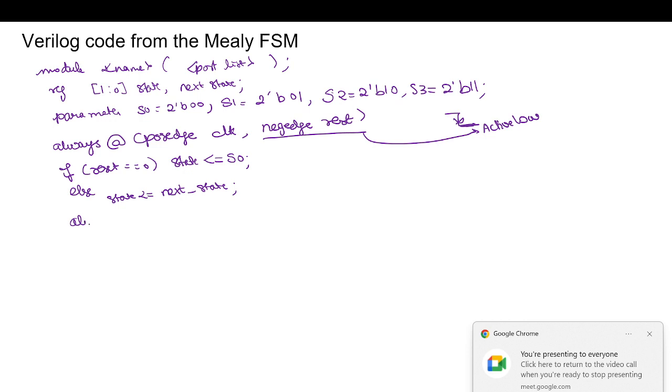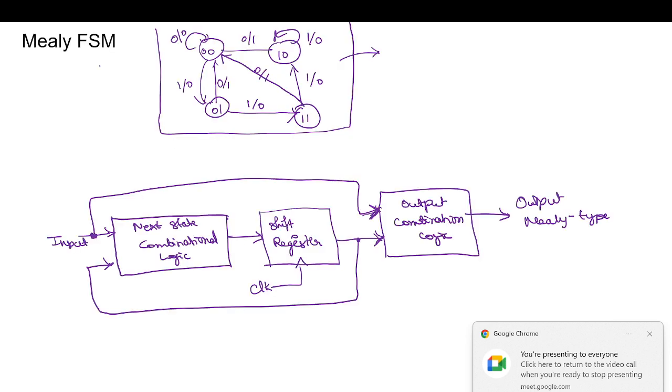And then for this always block, I have not written begin and end. So after this one statement, the next statement I will write inside another always block, always at the changes of the state or with the changes in the input. Case state. So S0, if X input is 1, it should go to 0, 1 state, S1 state. It should go to S1, otherwise S0.